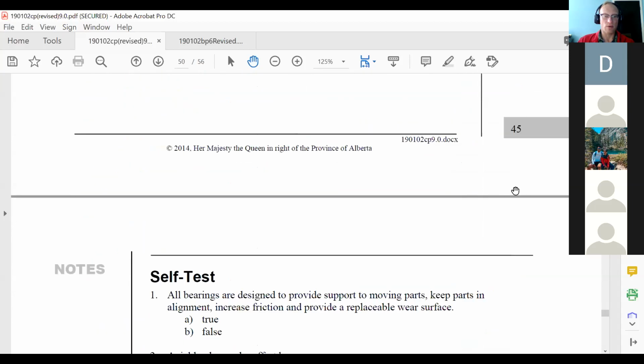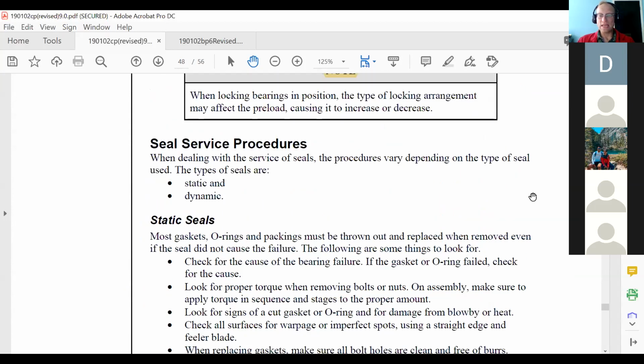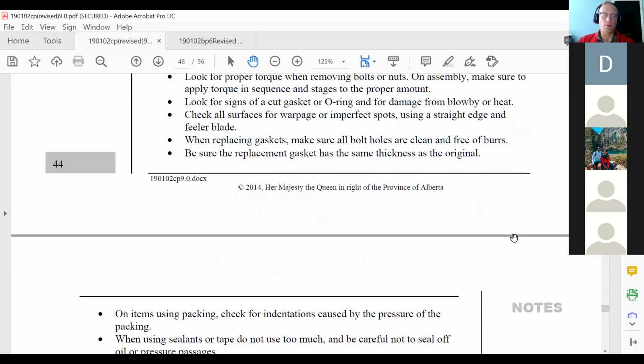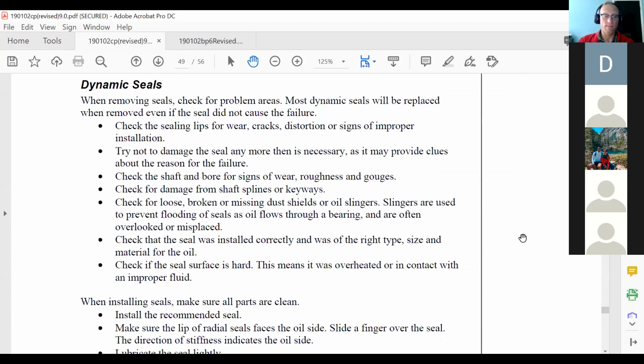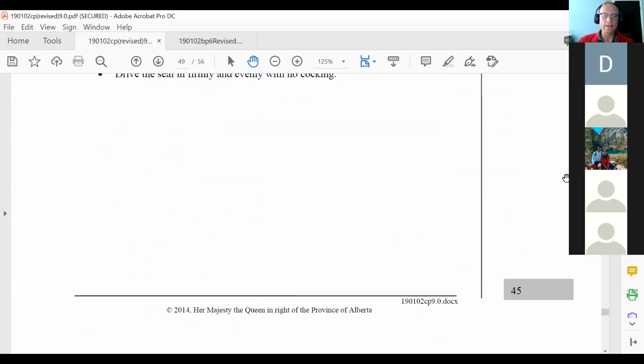Other than that, I talked about those seals a little bit. There's not too much difference. The main point of the seals, two things. Don't roll O-rings, lubricate them. That's how you don't roll them. And when it comes to seals, just like bearings, drive on the surface that is friction fit. That's essentially the gist of this. The proper tool to drive it in is the best one. Don't use sealants or gasket makers unless you're directed to by the manufacturer, okay? Other than that, this is all things we've talked about a little bit already.